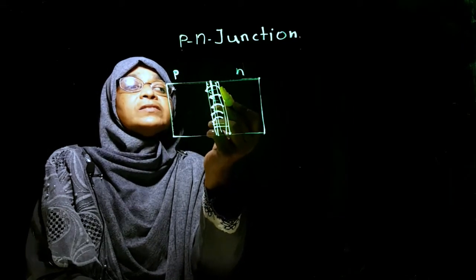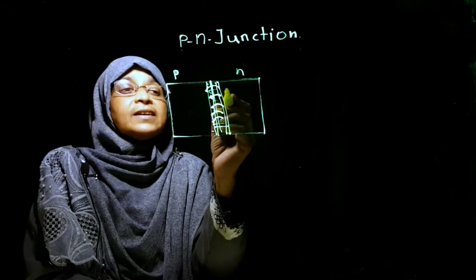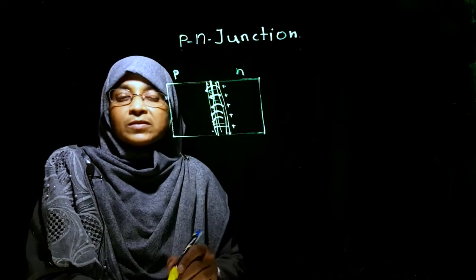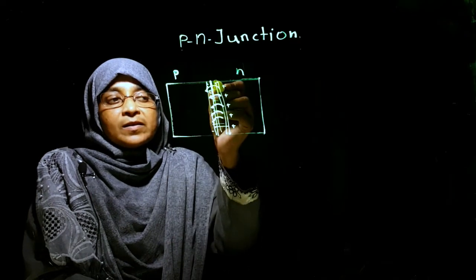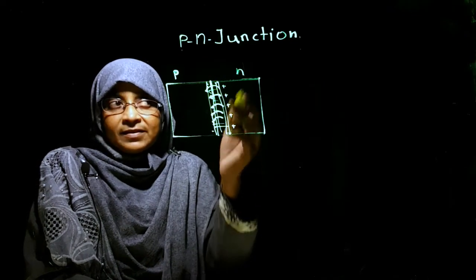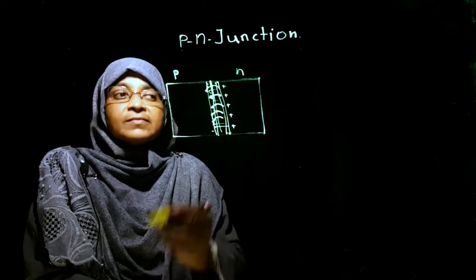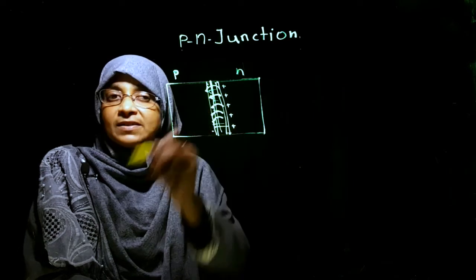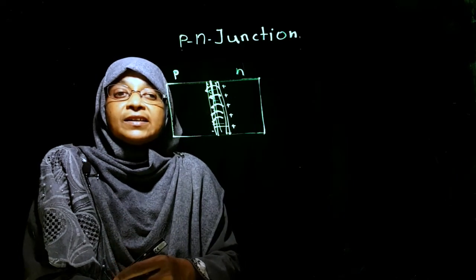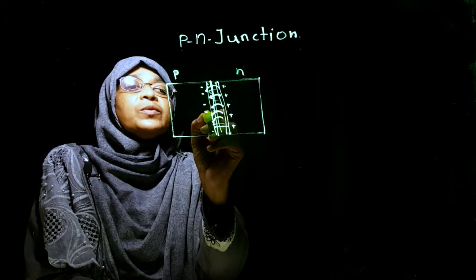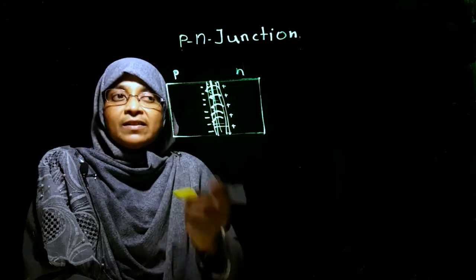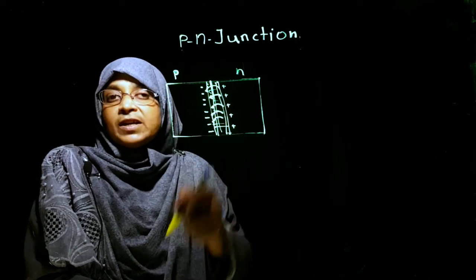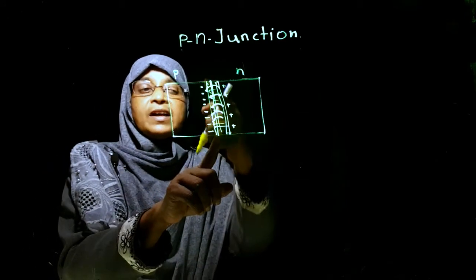As electrons leave this side, it becomes positively charged. Holes align on the inside. And when electrons build up in this p side, it creates a negative charge in the p side. A negative potential forms, and a positive potential forms. Between these two, there is a barrier.